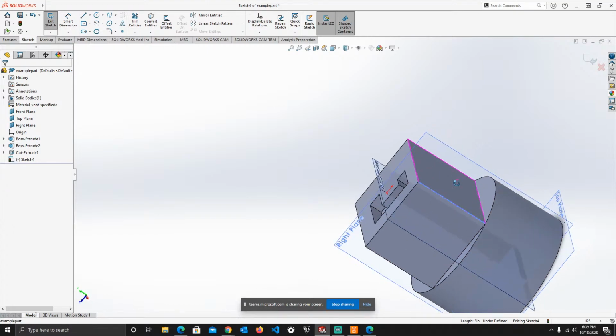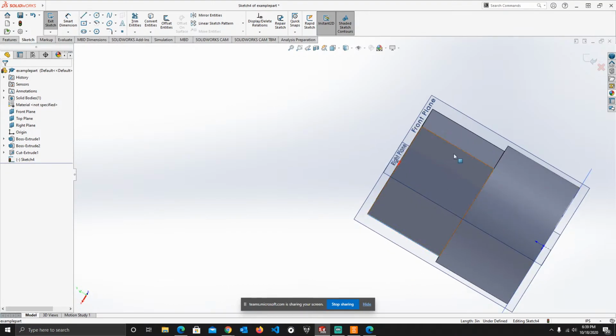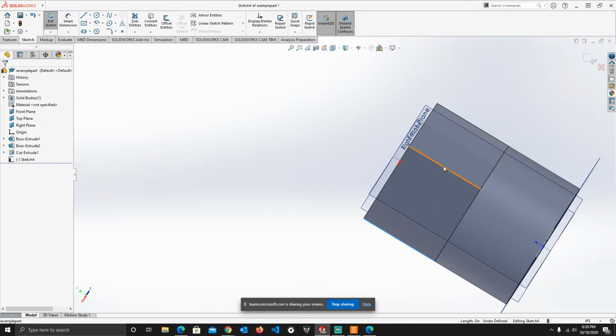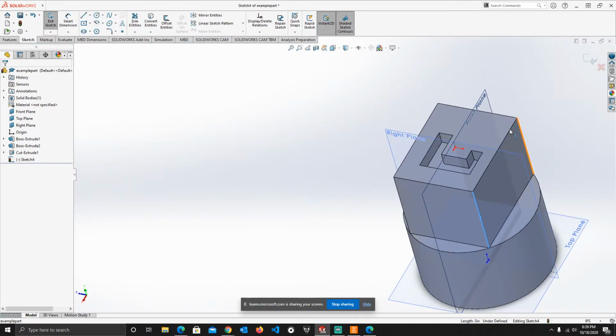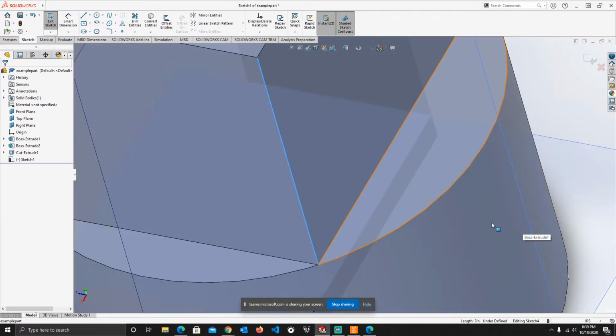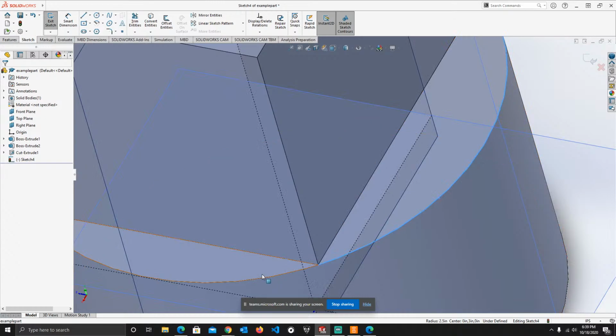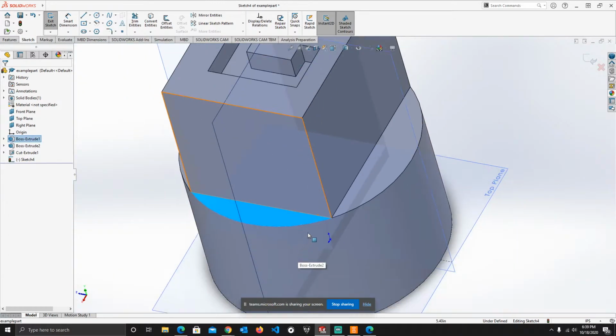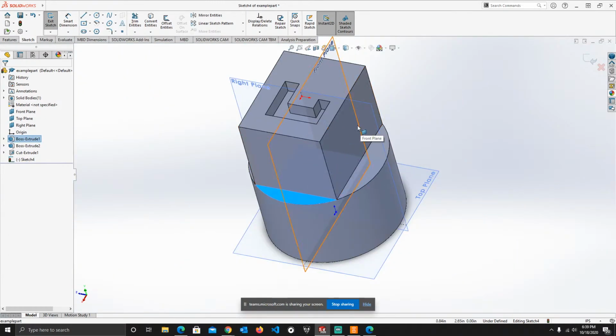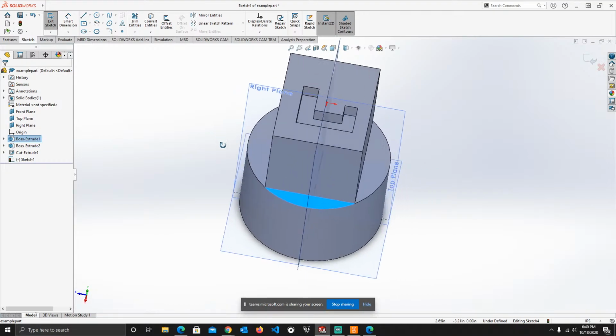You see how these contours right here, these edges, they are very sharp. If you were to machine this, right, you got a piece of metal and you're machining it, these edges are very sharp. So if you're making it for, I don't know, consumer products, or maybe you want to make a robot that doesn't cut you, then you want to do something called fillets.